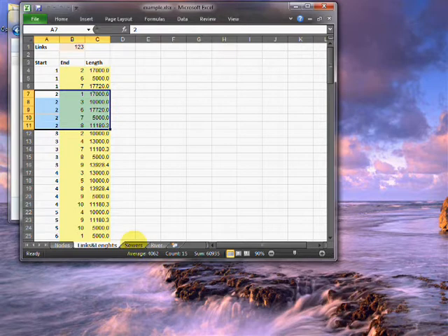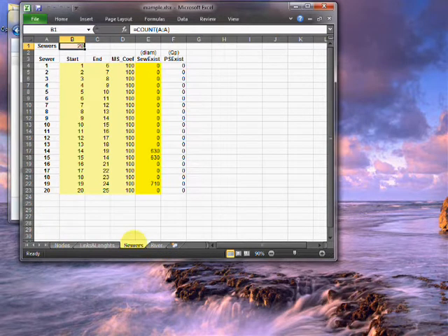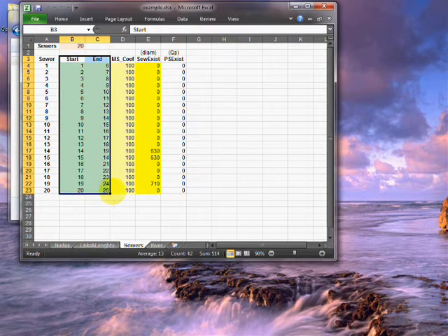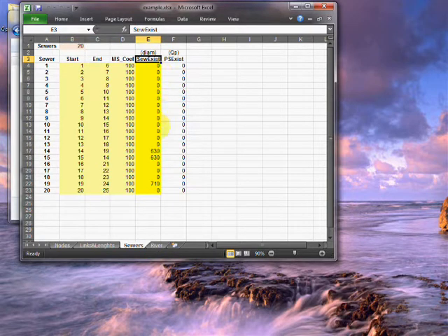The third sheet contains information about the initial solution from which the program begins its search for the optimal configuration. Only one sewer can start in each node. The sheet specifies all the sewer's start nodes and end nodes. Also, there is a column to identify its Manning-Strickler coefficient, required for the hydraulic model used by the program. The last 2 columns in this sheet relate to the diameter of possible existing sewers and the peak flow of any pump station existing in that node.